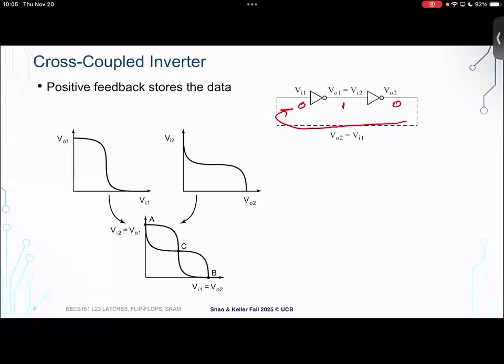Another way to think about or visualize the effectiveness of this storage cell is with these overlapping transfer curves shown in the bottom left of the slide. So if you think back all the way to lecture 2, I think, is when we presented these. There's either 2 or 3 where we presented these voltage transfer characteristic curves. So this should look familiar. This is the transfer curve of an inverter, right? It's saying that when the input is a high voltage, the output is a low voltage. And when the input is a low voltage, the output is a high voltage, right? It's doing that inversion.